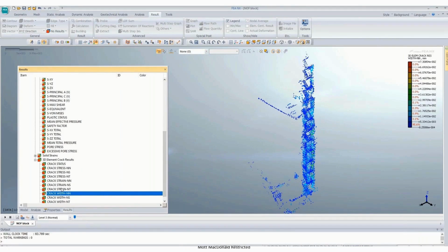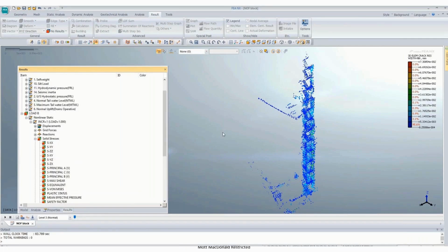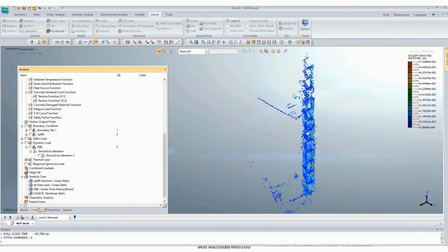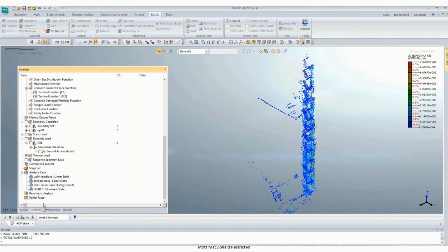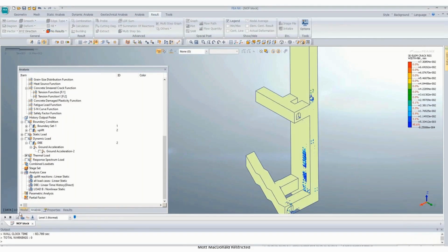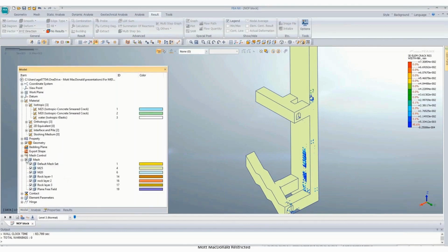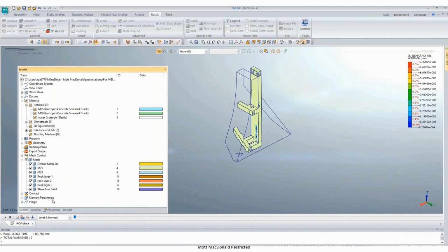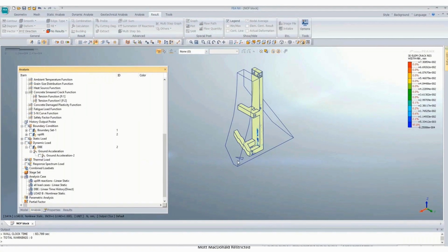From the numerical analysis, we can consider that our dam is safe for load case B. Stresses, everything, those are safe. Let me change it to shading with wire mesh, and then I can have the entire mesh open. Okay, so let's analyze for time history. Similar analysis can be done for A condition, C condition, and F condition, and check the crack widths.